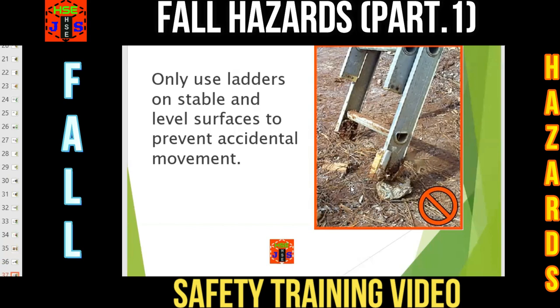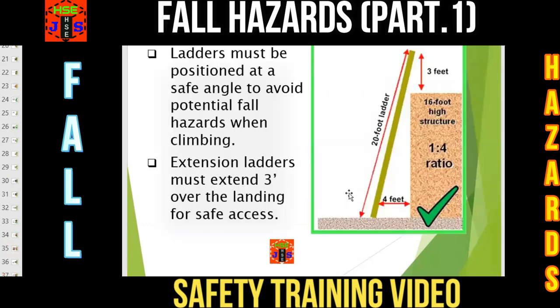You have to look at the ladders: how they are fixed, where they are fixed, and how the workplace is. Are ladders fixed on a level surface, compacted surface, stable surface, or not? Ladders must be positioned at a safe angle to avoid potential fall hazards when climbing.